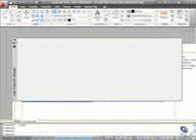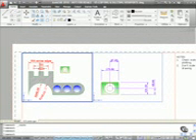So I scroll across a bit and I switch those ones off and switch the 10 ones back on, like so. Close the layer properties manager, and as you can see there, I've got dimensions 10 for the 10 viewport, dimensions 5 for the 5 viewport, and the dimensions 5 here that are the wrong size have been basically switched off or frozen in that viewport only using current viewport freeze.